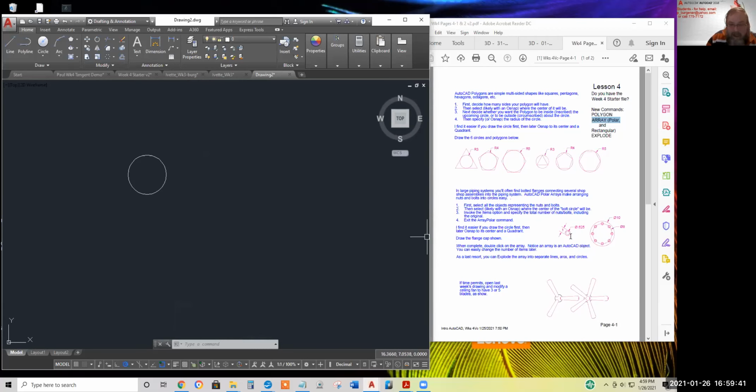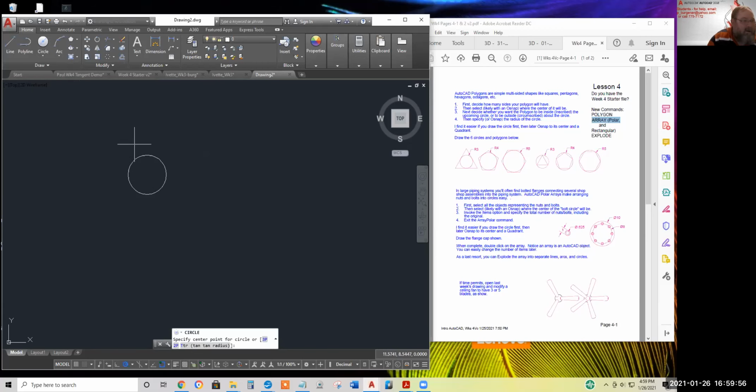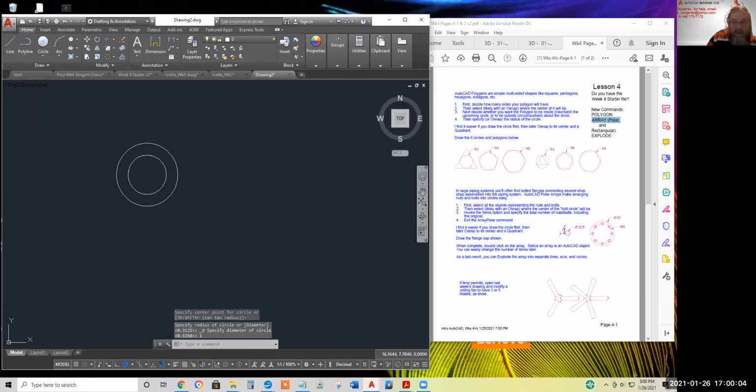Next is this hexagon. Note to self, print this out larger on the next handout. We'll draw a second diameter, hover, snap, 1 unit, and form the hexagon with the polygon command. Click on the polygon icon, answer the question. It's already 6 from the last time we used it. I'll hit enter to concur with the suggested default.